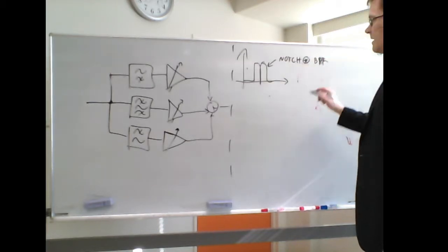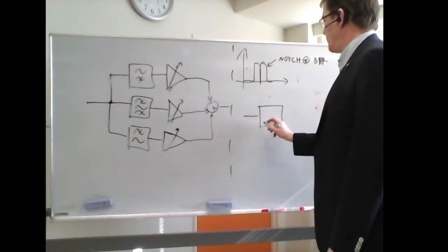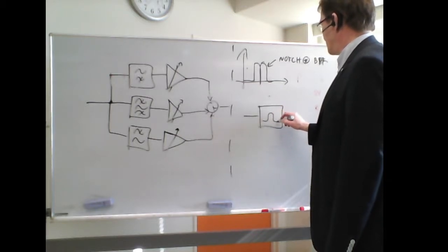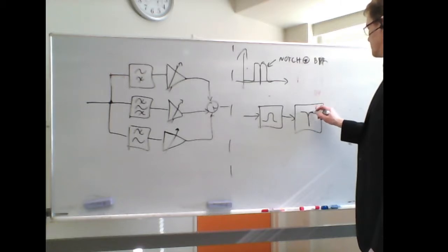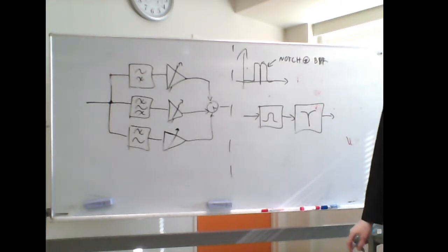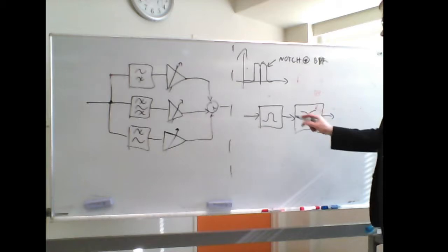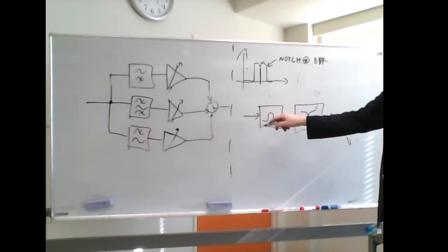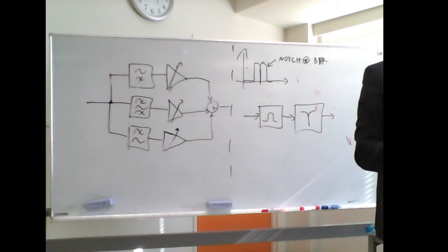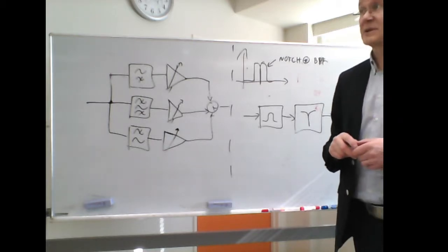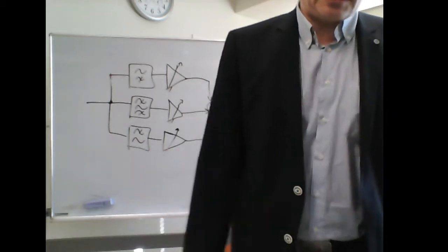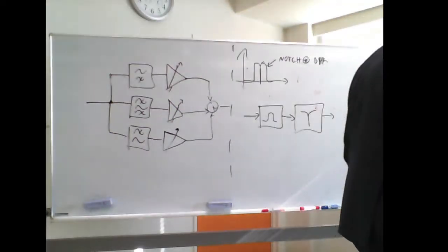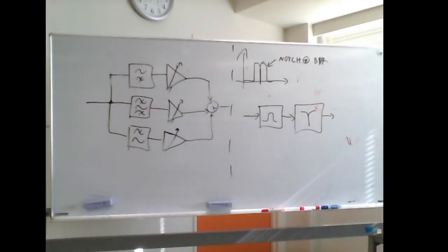The easiest way is actually to put the bandpass filter first and then the notch filter second. So signal to one filter first and then to the other. You can also mathematically calculate the total filter, but it doesn't help you. Okay, so those are the ways.